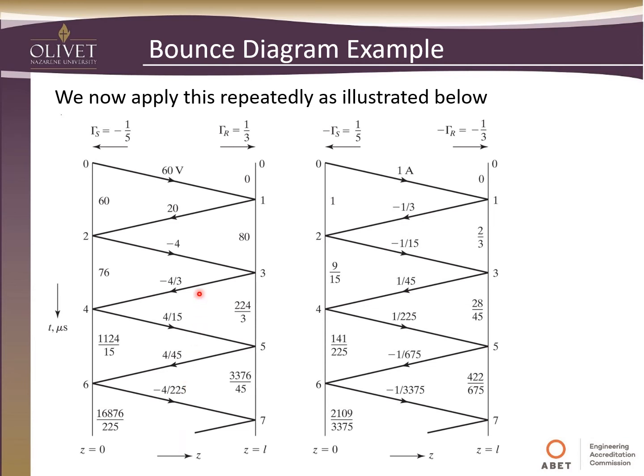But if you get up to really fast switching times in microseconds, you could hit in the middle of this somewhere. So like after 2 microseconds, you may not be sure if you have a 1 or a 0, or it may not be enough to hit the threshold of your logic gate. So that's where this comes into play. If you have some logic that's not functioning the way you think, or it's not consistent or repeatable, you may need to look at your switching times and adjust your clock speed to give this time to ring out or reach a steady state.